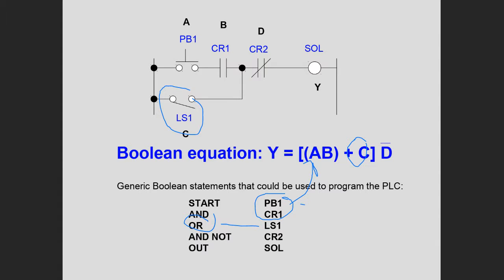And so in this way, you can actually enter in, without writing a ladder, the logic for a particular rung or set of rungs or program. So the most common way of implementing logic in a PLC is by far ladder logic, but there are some PLCs that understand Boolean logic, and as I said before, the structure might not be like what I'm showing you.